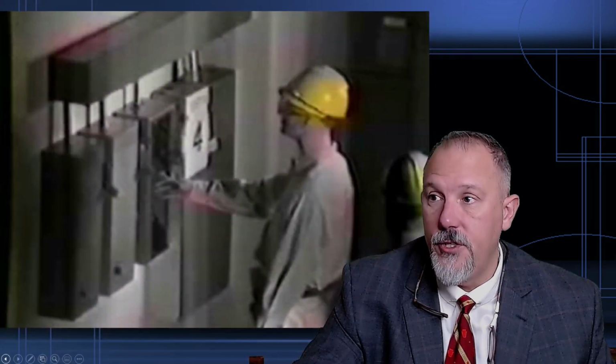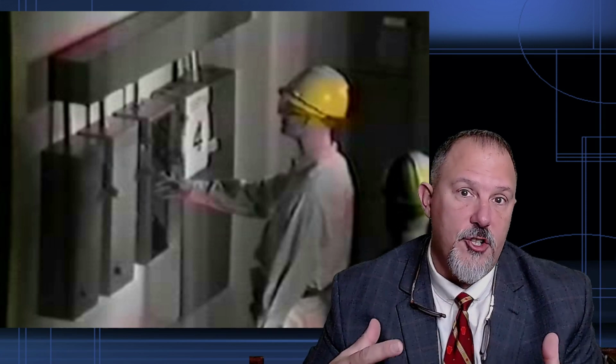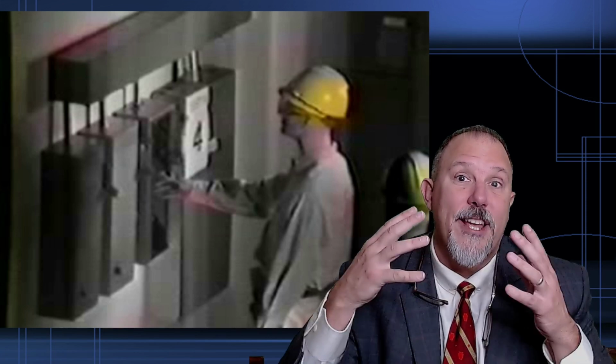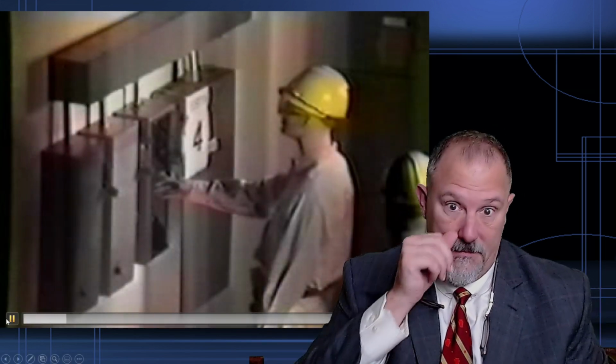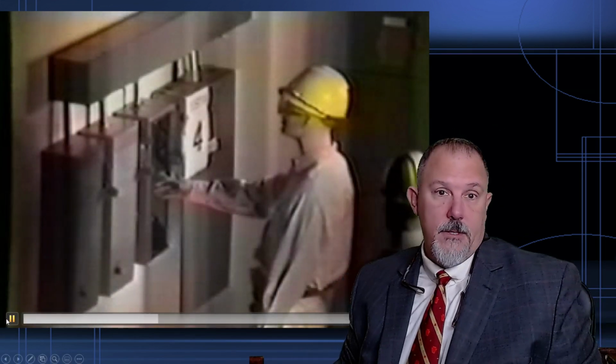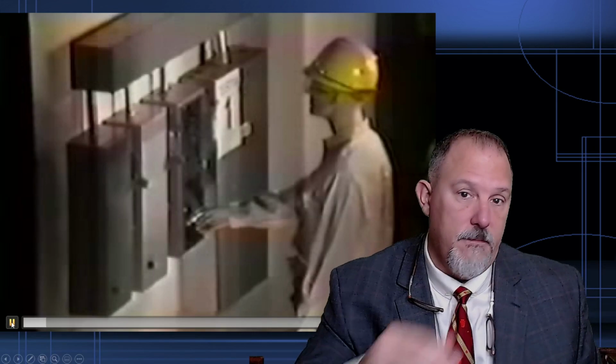And that's what fuses do best. They can reduce the amount of magnetic forces in a power distribution system, which can also reduce incident energy. We can take an event that looks like this. You could take an event that looks just like that, apply a current limiting fuse, and this is the result.